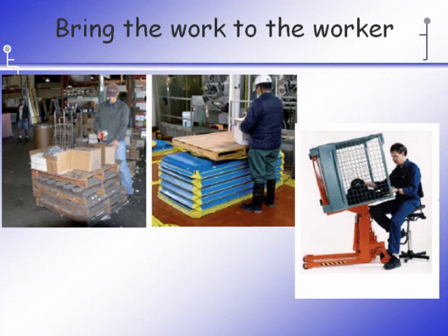As much as possible, whether it's the cheap solution, such as stacking pallets on top of each other, or the more expensive solution, the one in the middle, which is a scissor lift table with an accordion skirt on it, you want to bring the work up to the worker so they're not bending forward. Remember, the power zone is knuckles to shoulders, and that's where we are not only our strongest, but we're able to maintain those postures for longer periods of time without having undue postural stress.